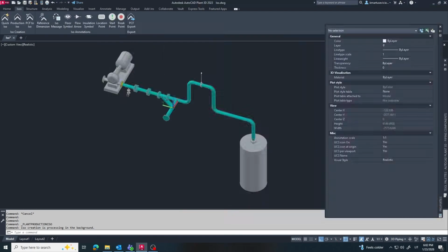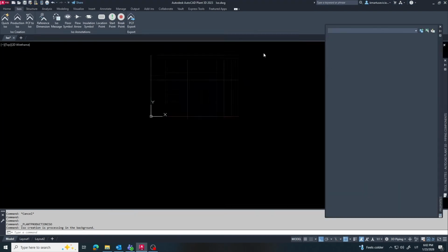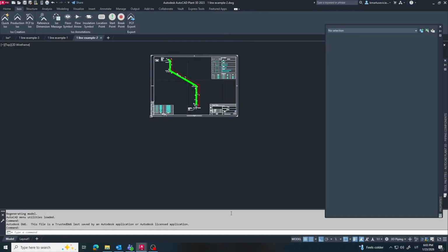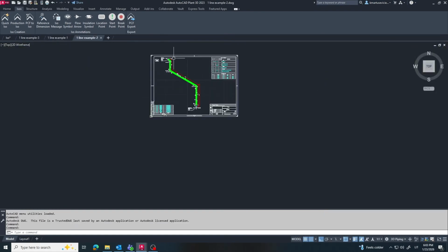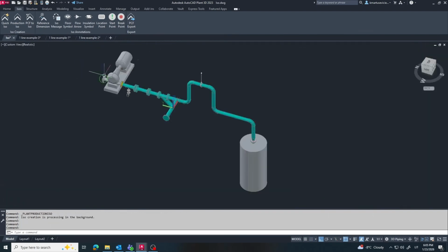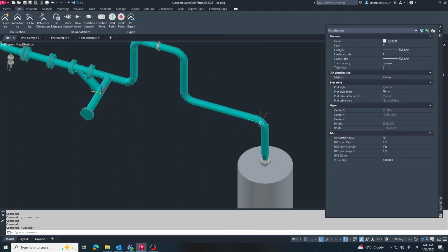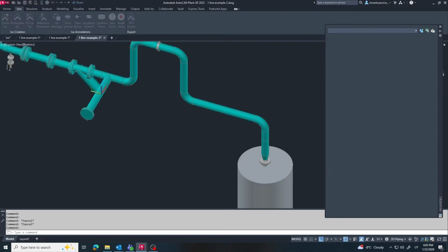As you can see, the ISOs are generated in a new folder. This pipeline is split into 3 pages, but I always try to minimize the number of pages. As I mentioned before, here we have the part names. In real projects, these usually need to be written differently, including part name, type, diameter, material number, and similar details. We've changed the part name in the Properties panel. So let's regenerate the isometrics and see if the name updates.